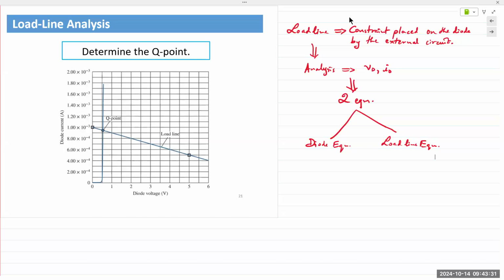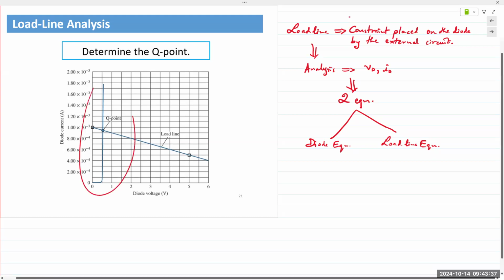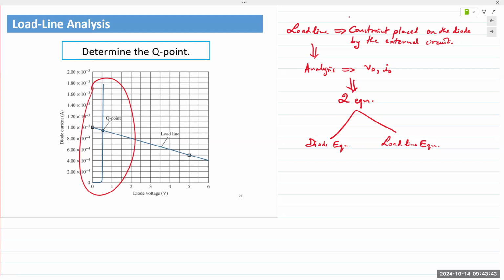The diode characteristic, as an engineer, you can obtain from the manufacturer, or if it's not provided, you can obtain it from the spec sheet and create your own. The manufacturer will provide a spec sheet with all the relevant values: saturation current, transit time, junction capacitance, series resistance.